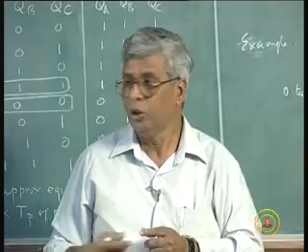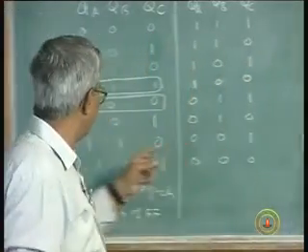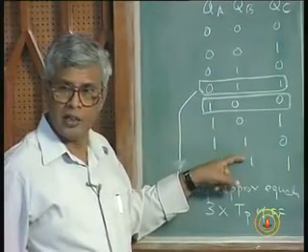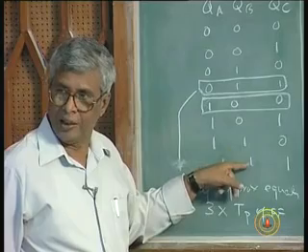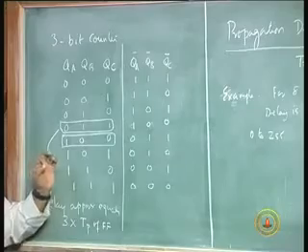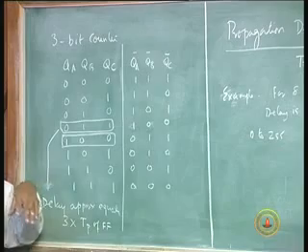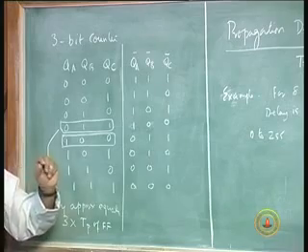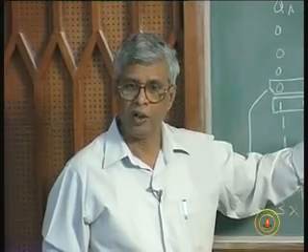There may be no change, for example, from here to here in this flip-flop, so it is going to come immediately. There is no change, so there is no question of propagation delay. It is not that each count is going to take the full delay. So I should allow for a maximum propagation delay of 8 times Tp in order for a count to be reliable.